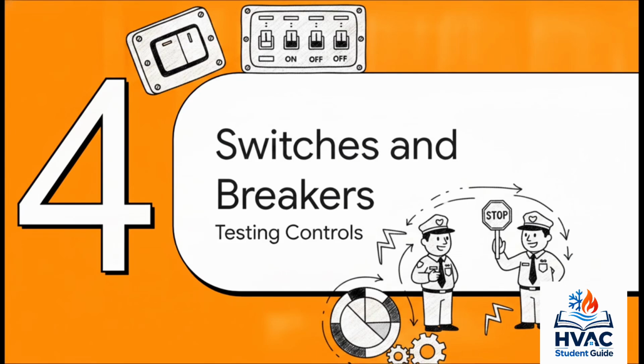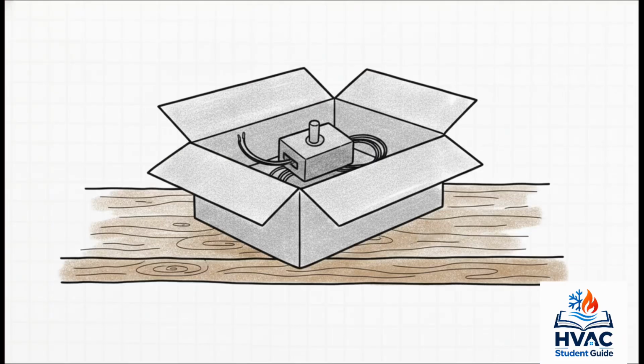All right, Section 4. Testing switches and breakers. So switches are placed in series with a load, right? They're kind of the traffic cops controlling the current. They come in 2 primary flavors, normally open and normally closed.